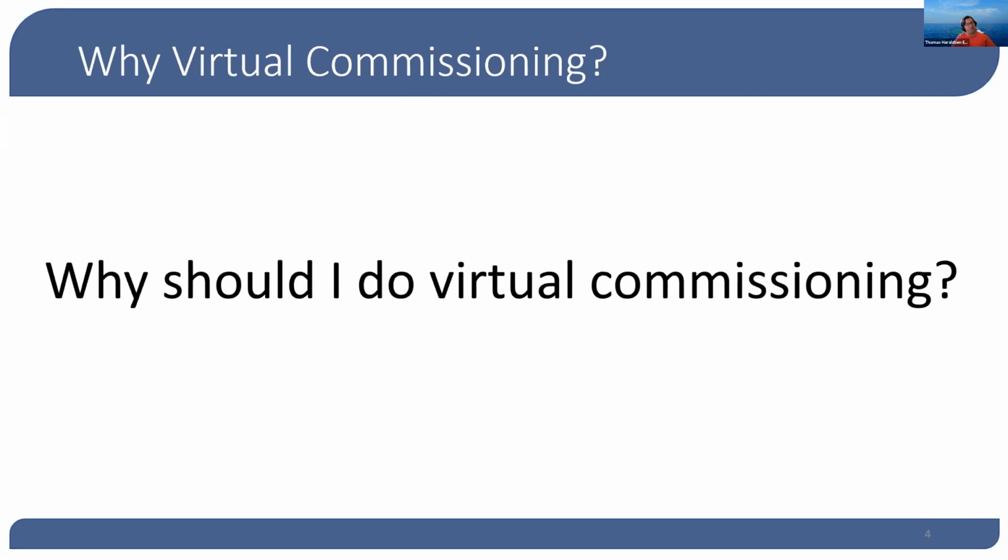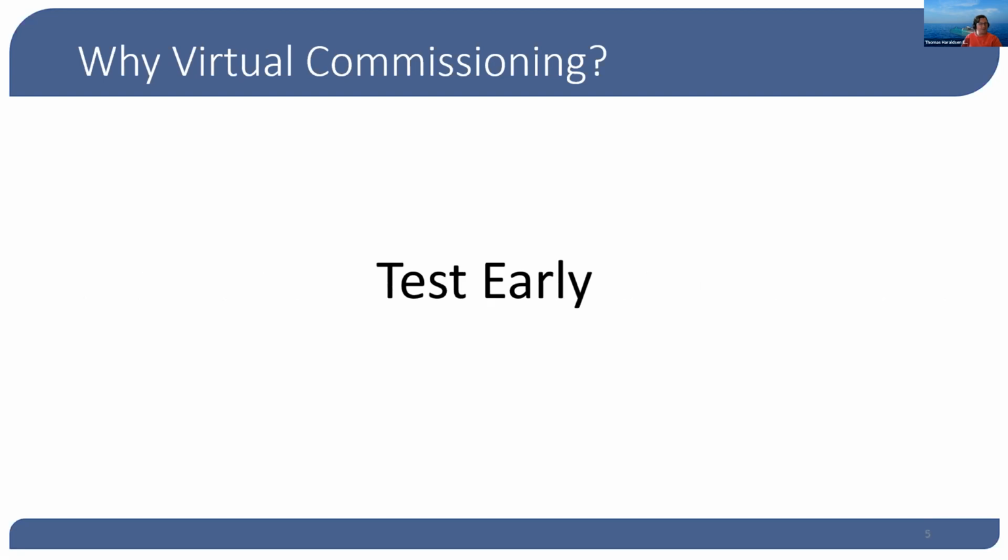So why should you bother with virtual commissioning? I think there are many benefits to gain from this way of working. One of them is you can test early. By testing early, you extend your testing period and thereby increase the probability of finding errors. And you also detect errors earlier in your process. This is the left shift that Kristine talked about, meaning that when you uncover errors early, they are easier and cheaper to fix.